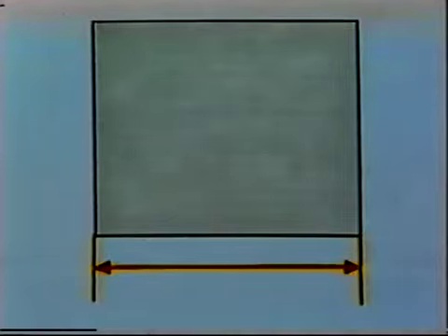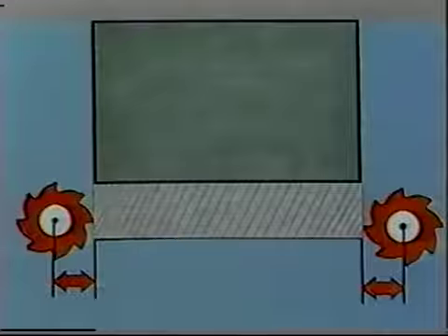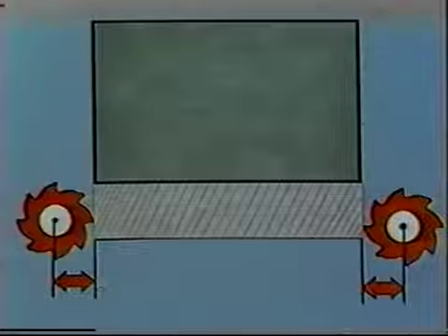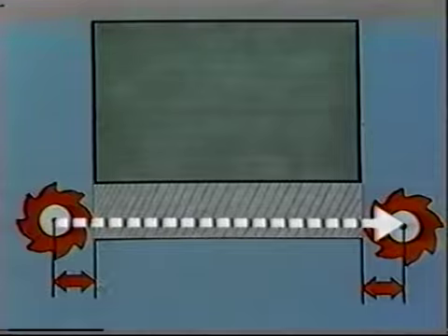No, that's ancient history. In the old days, if you wanted to cut a 50-millimeter edge using a manually operated machine, you had to account for the tool radius manually. The tool radius had to be added at the beginning and at the end of the traverse. The traverse path had to be longer than the edge to be milled by 2 times R. With old-fashioned control systems, all of this had to be calculated too.